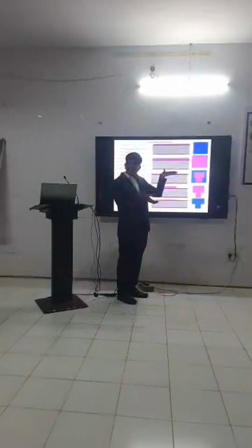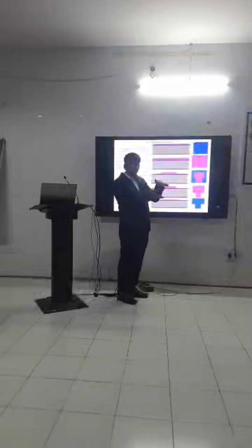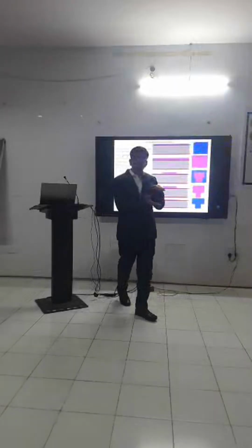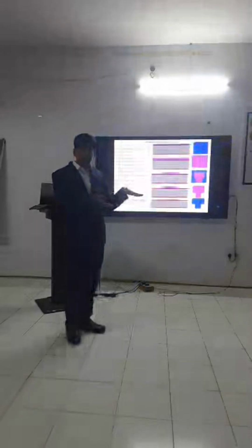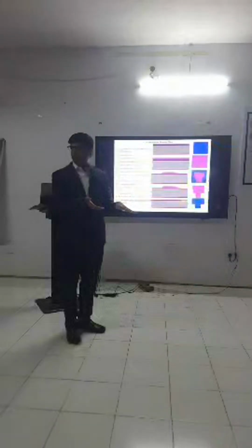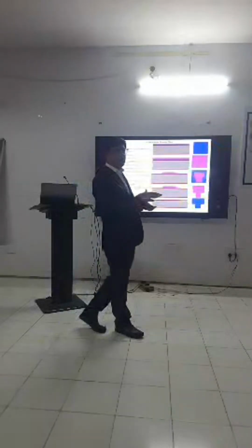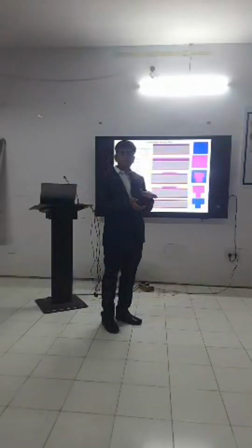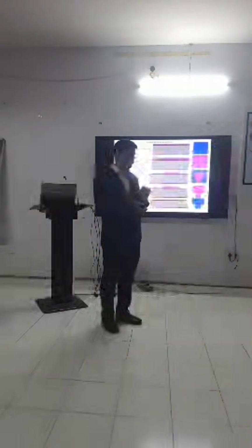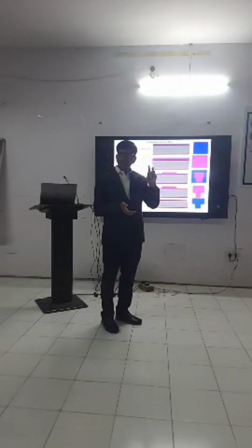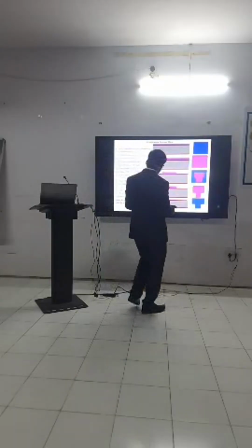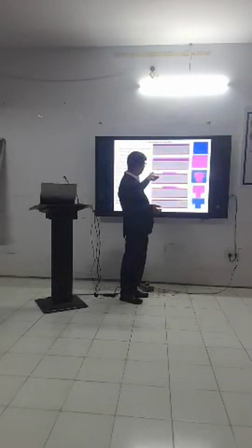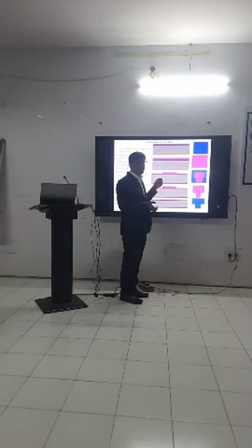Because we have seen how to design the mask, so we have that mask plate. What will this mask plate do? Because we are using bright field lithography, wherever there are bright areas, UV light exposes directly, and wherever there is a dark area, UV light does not expose your photoresist. So the brighter area will become softer and the darker area will become stronger. Once after UV lithography, we will put my silicon wafer into a developer. Then what will happen?